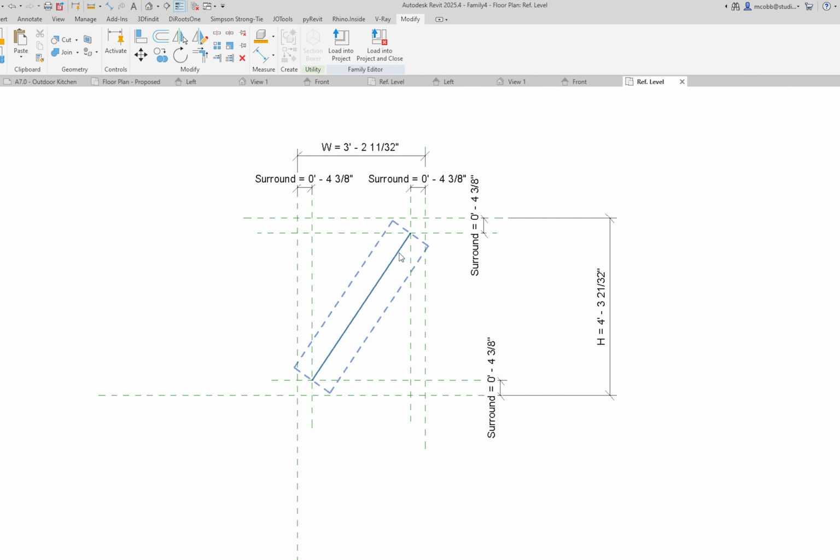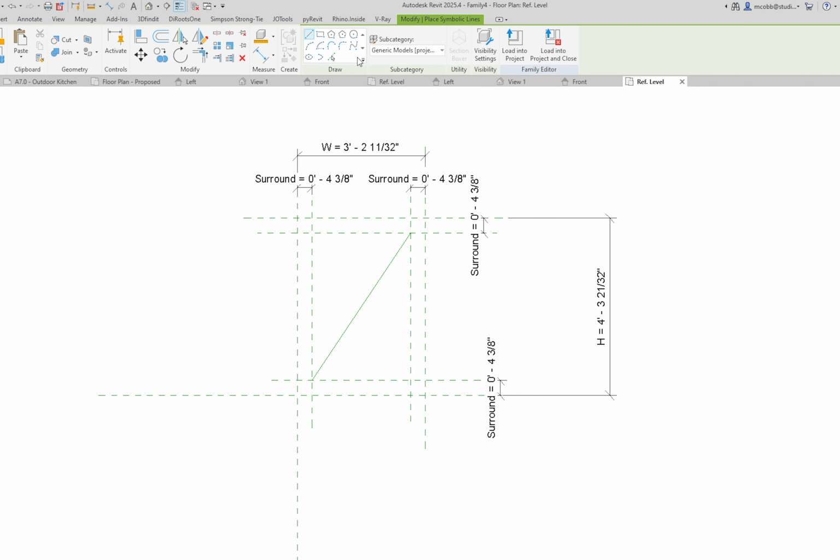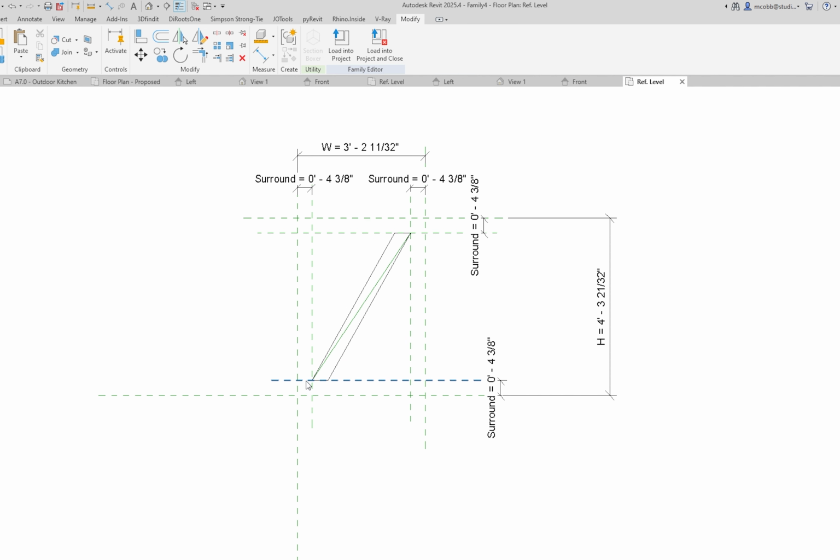Okay, so we have that much now. Now we should have this dimension already calculated. Now to get what we're trying to do, and I'll just quickly draw this before we do it, what I'm trying to do is a Z-brace that comes here, comes here, comes down here, and basically forms a parallelogram where opposing sides of a board are intersecting the corner condition.